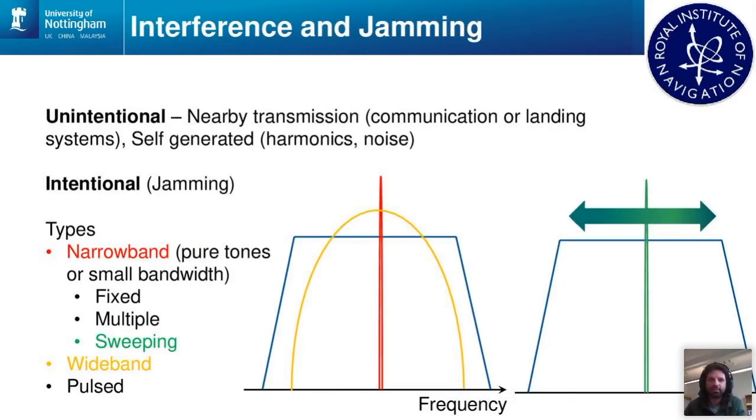In terms of interference, we have a number of different types. We've got quite a lot of cases of unintentional interference which can affect a GPS receiver. Because the signal levels are so small, our RF sections, so those antenna and front end sections, are very sensitive to noise just in the integration of our GNSS chips into the system around it. So there could be a number of noise sources that a GNSS receiver has to deal with that are entirely either self-generated or generated from sources nearby, entirely unintentional: communications devices, any interference from other sources like Wi-Fi, Bluetooth, whatever you've got transmitting around you. Then we also have types of interference that are intentional, sort of malicious, which we might call jamming. So somebody actually trying to stop our GNSS receiver from working.